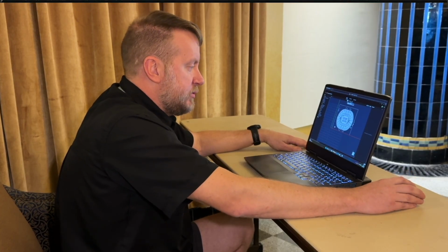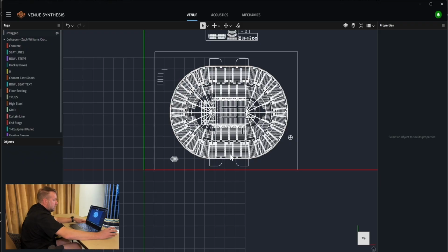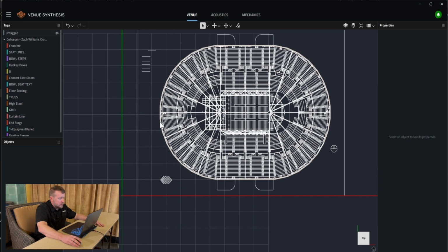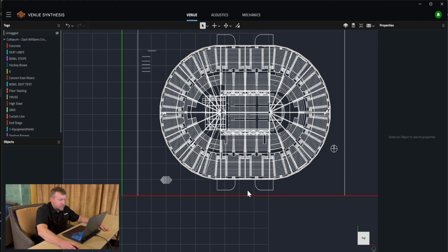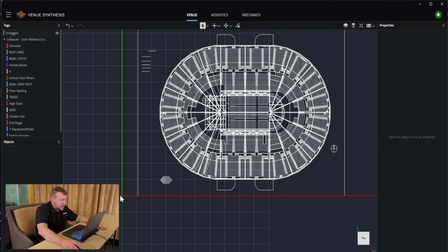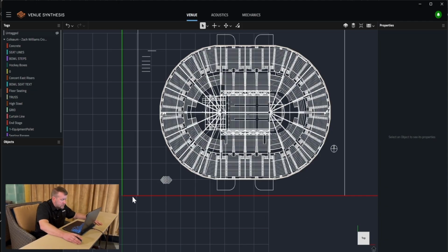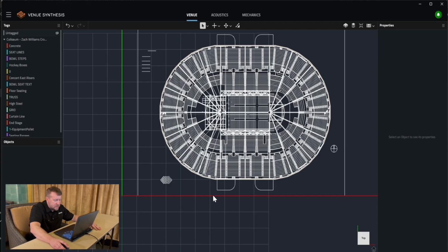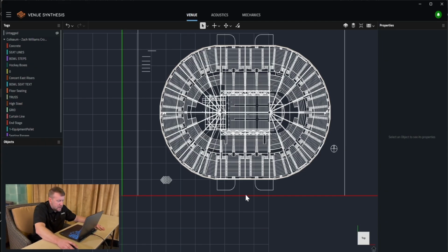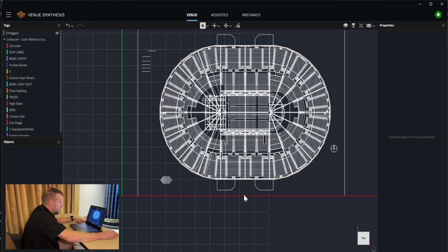The first thing we need to do is move this DWG to our origin point. This is a challenge here in America because we work in feet and this grid is set out in 10-meter squares. So here we have to estimate how many squares we have to shift it. Horizontally on this X, we need to shift 1, 2, 3, 4, 5, 6, 7, 8.5-ish grid squares. Vertically, we need to shift 1, 2, 3, 4, 5.25. We can do some math on that.